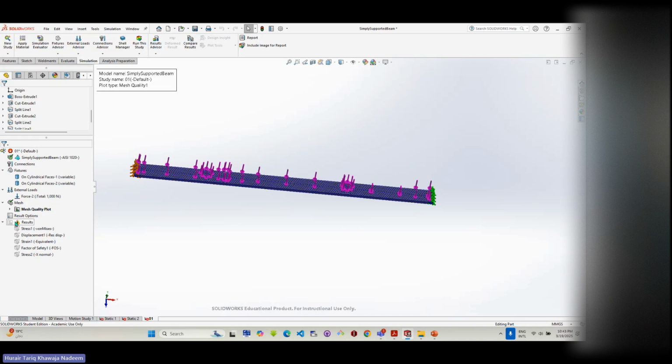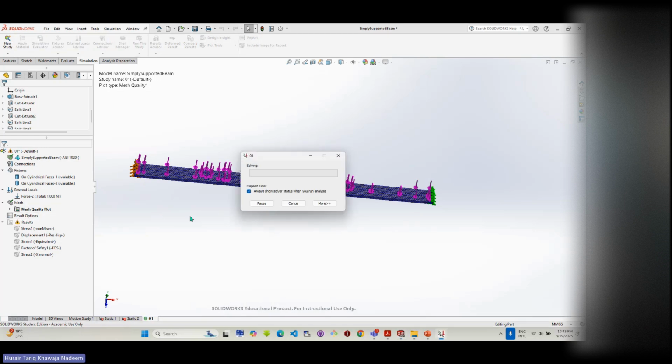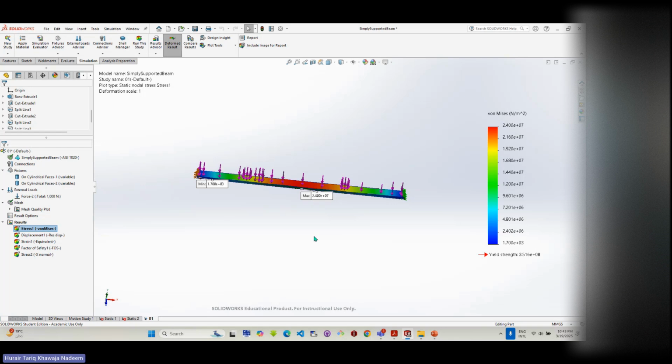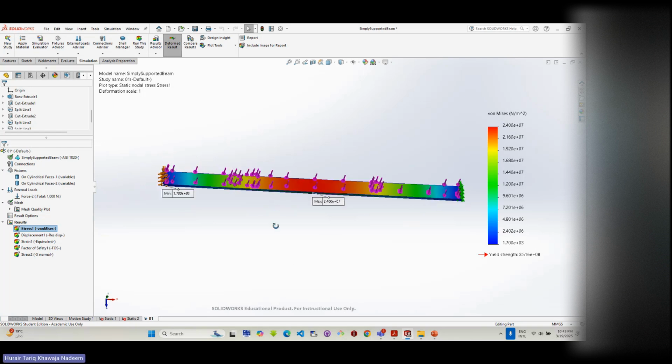And then click. If you have a yellow, this means there is a trouble. So you always have to make sure that the yellow goes away. Okay, look over here, the red is gone. So this is done. Now, what I was saying, I forgot. Yes, I made a split line, isn't it? So I made a split line over here, which is this one.